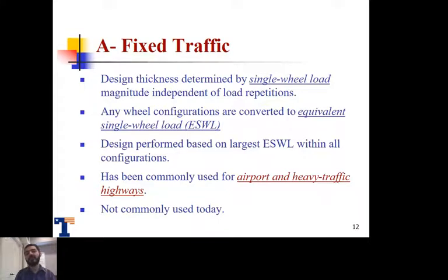In the fixed traffic procedure, we are trying to design thickness determined by single wheel load magnitude independent of load repetition. So here we're looking into a certain wheel that we typically see repeated over and over, and we try to see that any wheel configuration can be converted to this equivalent single wheel load, which is ESWL. So the design typically here is performed based on the largest equivalent single wheel load within all the